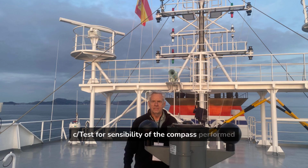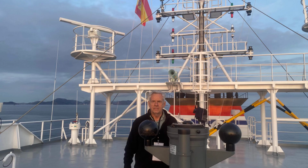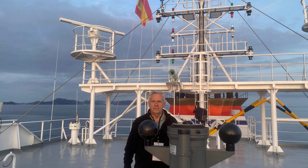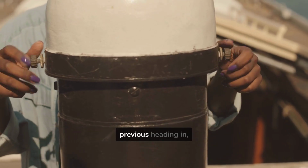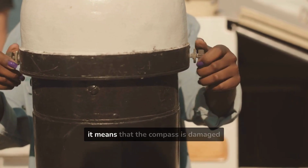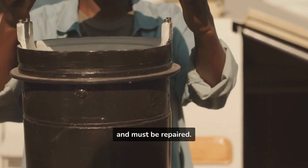C/ Test for sensibility of the compass performed with a magnet. It is made by writing down the actual magnetic heading and then approaching the magnet to the compass. If the compass does not recover the previous heading in, let us say, a few seconds, or it is blocked, it means that the compass is damaged and must be repaired.